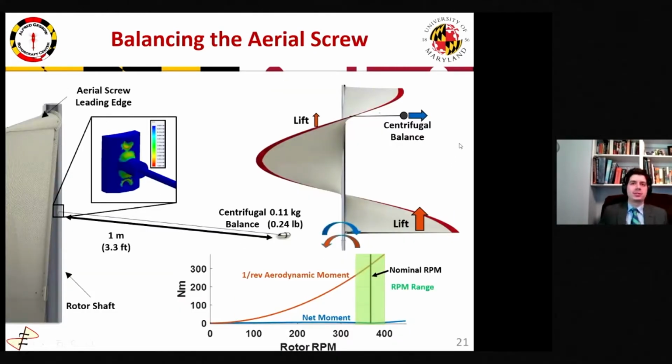The final challenge for the rotor design is keeping a single-bladed rotor well balanced. The aerodynamic forces are not distributed symmetrically over the surface. Additionally, even if the CG is located over the shaft, there's a centrifugal moment generated due to the rotor height. A combination of these forces ultimately snapped the shafts of a few tested rotors and would prohibit Helico from flying if